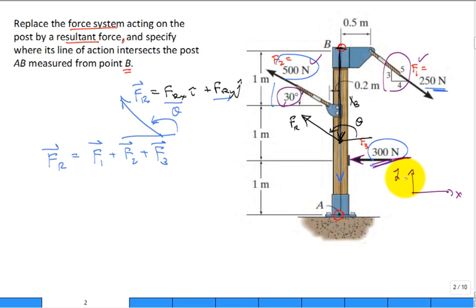All right. So when we do that, we come in with the force resultant, the magnitude. F is equal to 542 newtons. And this angle theta for that resultant force is very large. Theta is 169.4 degrees, meaning it's almost 180 degrees. So I've exaggerated it; it should be even closer to that negative x-axis. So that's the first part.